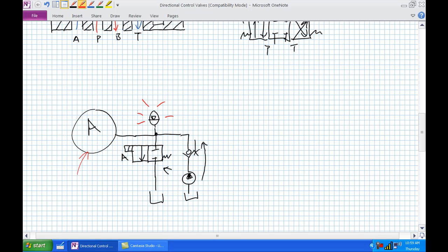Okay, let's say we're going to go ahead and work on this thing. We turn off the pump. How do we get rid of stored energy inside the accumulator? Well, we energize solenoid A, it shifts to our dump position, and our accumulator dumps. Okay, so that's the difference between our normally closed and normally open hydraulic valves. Okay, so accumulator bleed downs, ons and offs.